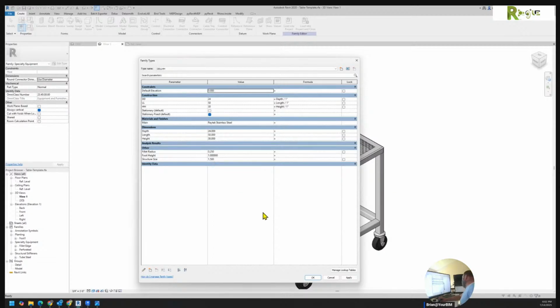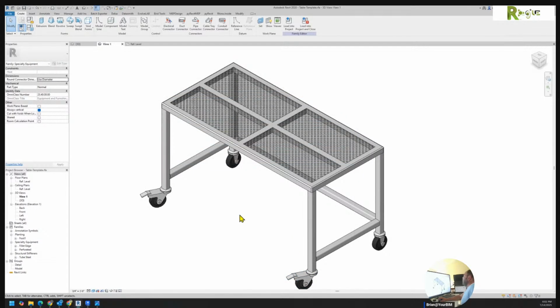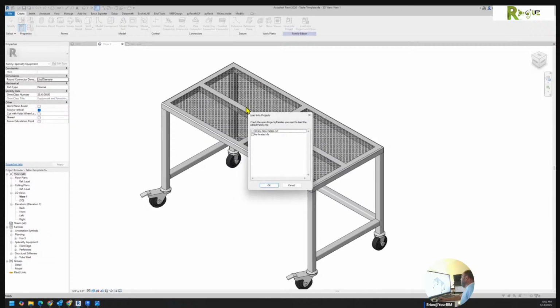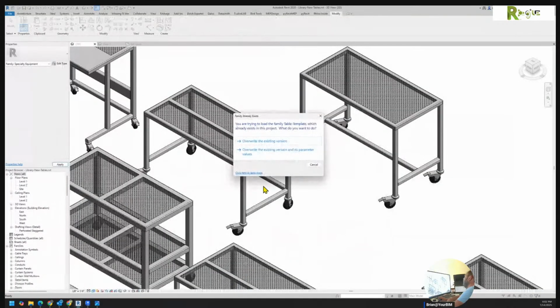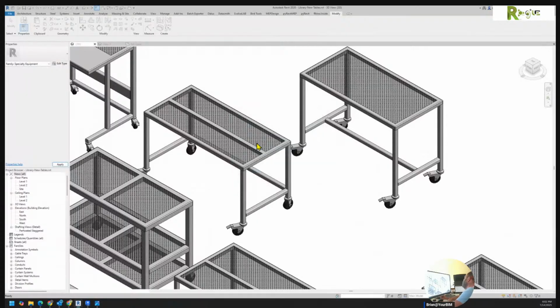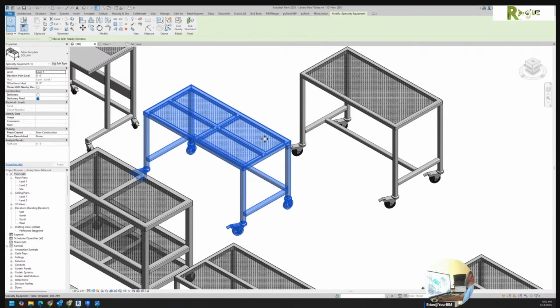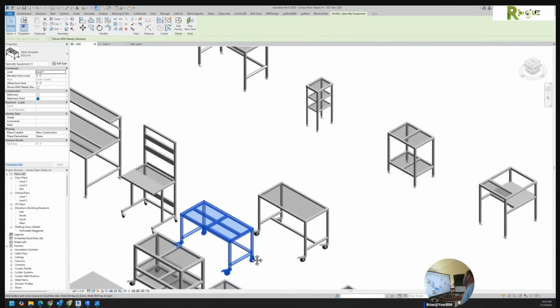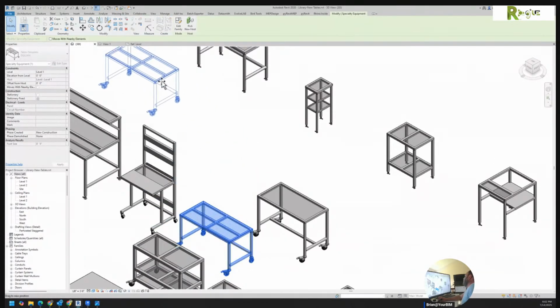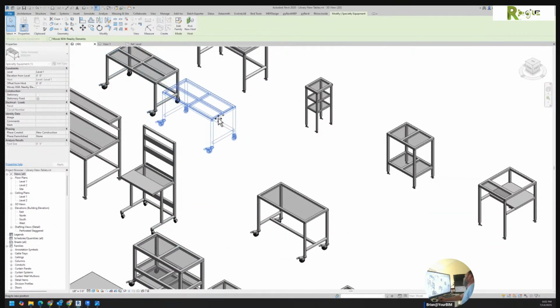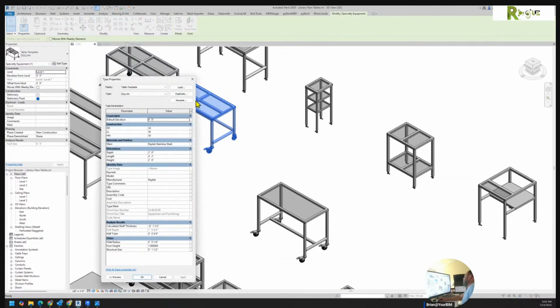Now, why did I think that was important? Well, because I thought that it might be beneficial. And watch, we're going to do this in the actual project. So we're going to load this guy back into the library template new. We should see him update. Ready? He should get 4 grids instead of 2. Oh, there he was right there. That guy right there. So what is the benefit? Well, I can take this family, and if I copy it down and say edit type and say duplicate, I'm not even going to number it, but you see what it is,